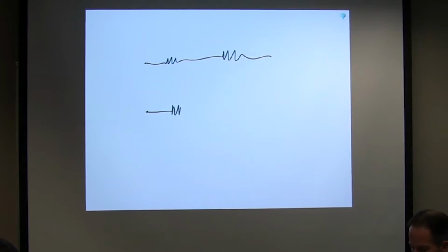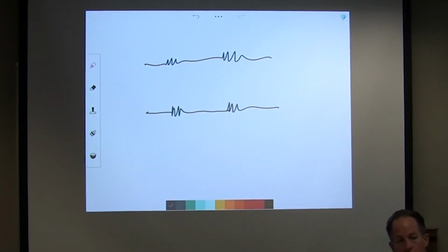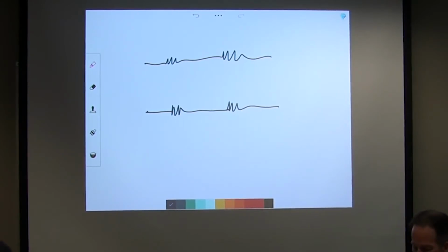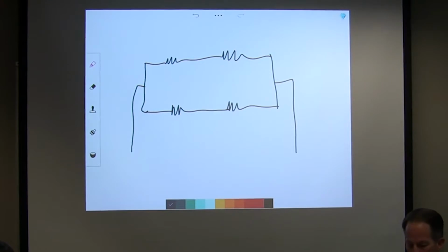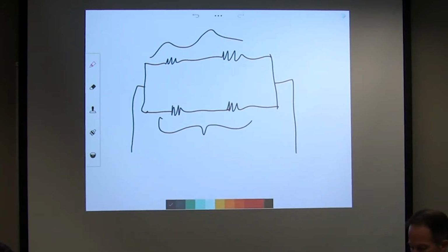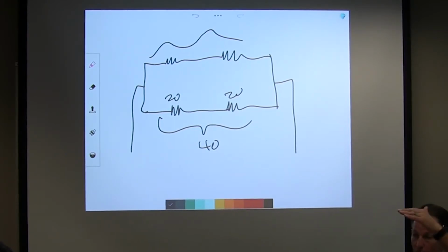We take a resistor, or a thermistor, I should say, and we put 4 of them in some sort of air handler for mixed air or whatever. And if we hook them up like we did in the lab, series parallel, they look just like one sensor, right? You remember how these 2 together are doubled, so if we're doing our lab, we got 20, 20, so that's 40, but then 2 40s in parallel, half it back to 20, right?